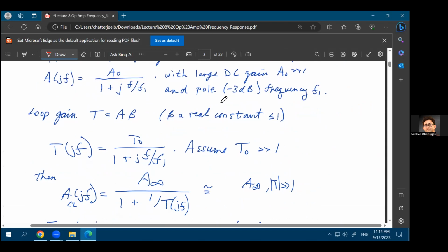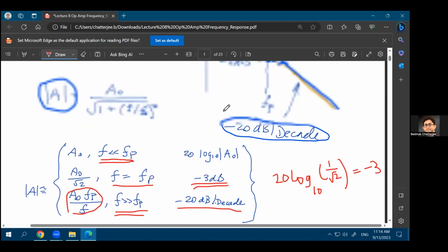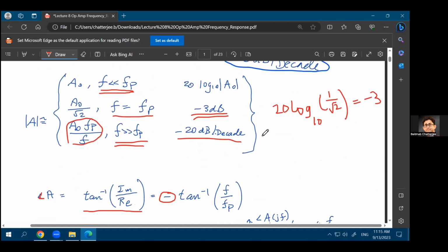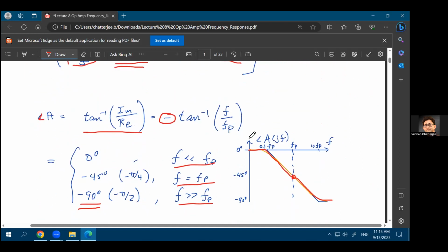That usually you'll consider this as a single pole low pass filter, because at the output you have that R0, the output impedance of the amplifier, and you'll have a parasitic capacitance anyway. And if not a parasitic capacitance, you'll connect this amplifier output to some input. Let's say you connect it to another amplifier. So you are talking about two-stage amplifiers, right?